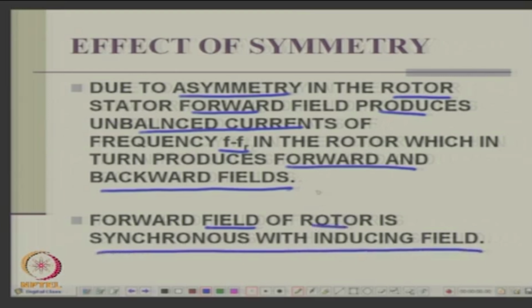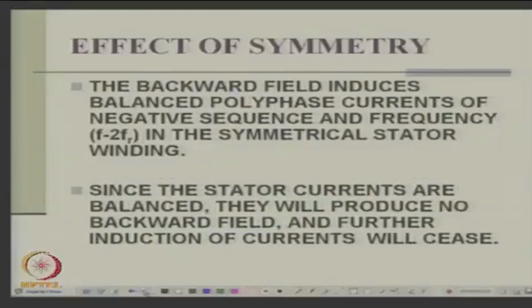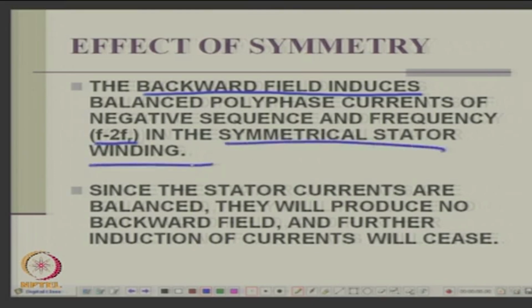But the backward field of the rotor will induce a frequency F minus 2 Fr in the stator, but fortunately the stator is symmetrical and it will not produce any more fields back into the rotor.